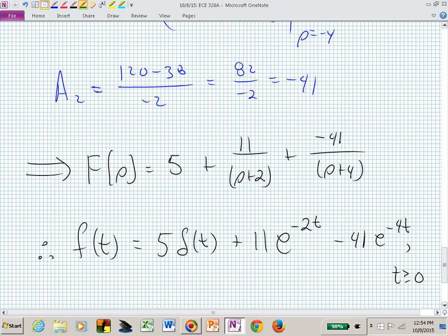And what did we say last time? Oh, if that actually becomes e to the minus 5, then effectively that term is gone. And so we're looking at 5 time constants. We're setting 2t equal to 5. And now what do we end up with? We get a settling time of 2.5 seconds. So in 3 seconds, you can basically, did anything happen? It'll all be gone for this particular f of t.